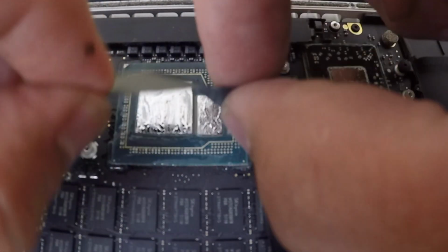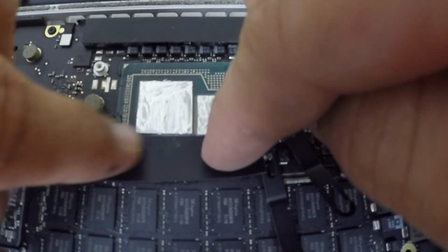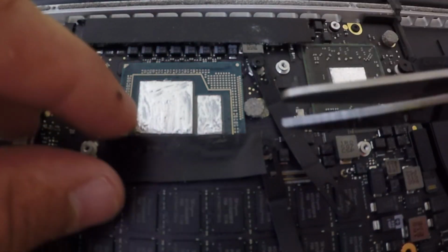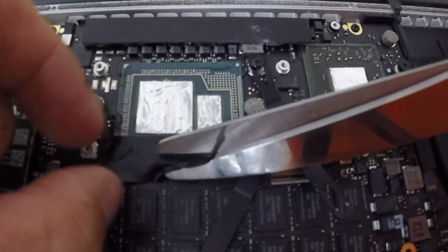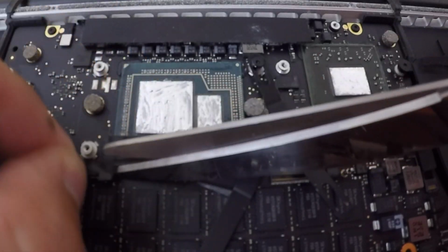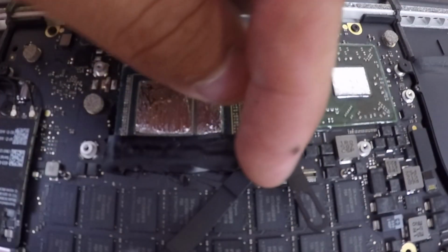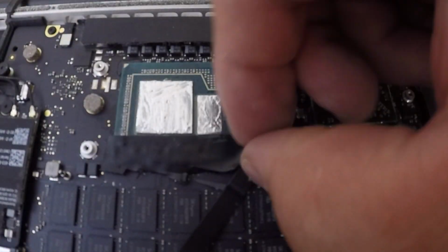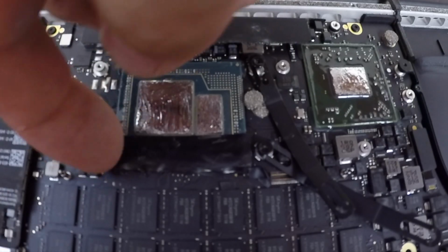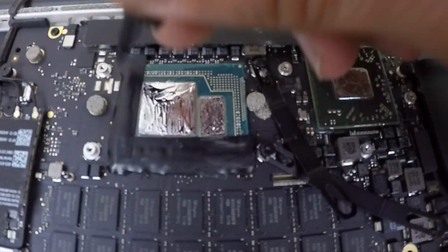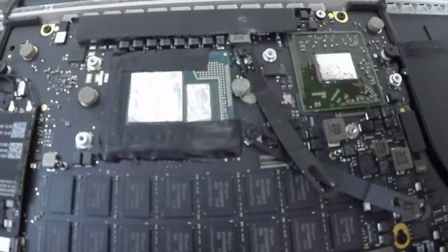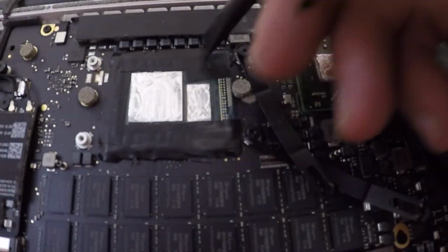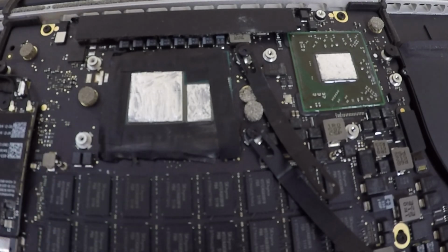So I made several mistakes in the video. One, I should have taken the electrical tape first and put it on the CPU and GPU board, and taken a pry tool and pushed on the corners and the tape to make it really flush, or stick to the actual CPU board and GPU board, so it makes a real good barrier. My biggest mistake was I used electrical tape that's only rated for 80 degrees Celsius or 176 degrees Fahrenheit, and the CPU and GPU can get up to 100 degrees Celsius.